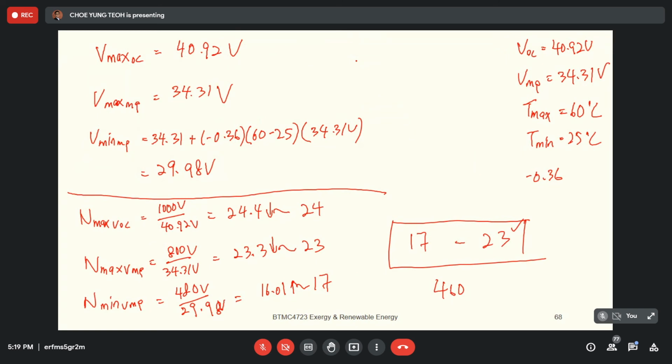Okay, so based on here, we can estimate the power output from the panel already. Normally, how much you can get in Malaysia, maybe just around 20% of the capacity factor. If you do not have a system to calculate, the software to calculate, you can just roughly estimate, maybe just around 20%.